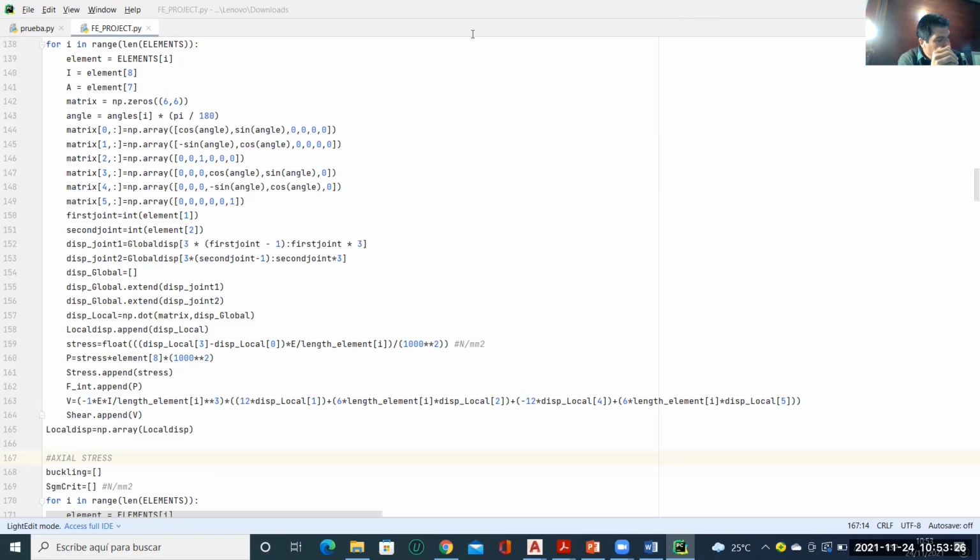Remember, you always have to do a convergence analysis in order to be sure that your results are close to the correct one, because we do not know the analytical, the precise results. So we always have to be worried about how close our result is from that precise, exact analytical result.